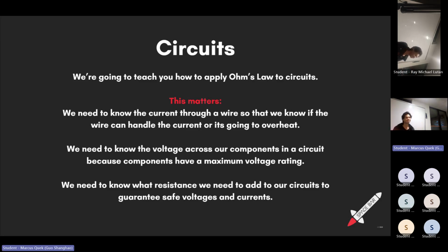Are there objects that do the opposite? Yes, but don't use them. Usually it's heaters which have this thing called a positive or negative temperature coefficient, which says how the resistance changes as it heats up. You can read more into that later, but it's very useful in some cases and very scary in others. There's a sensor called a thermistor, and there's PTC and NTC. PTC is where the resistance increases, and NTC is where it decreases.